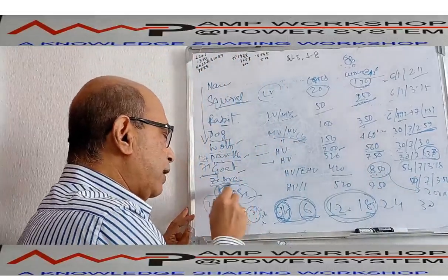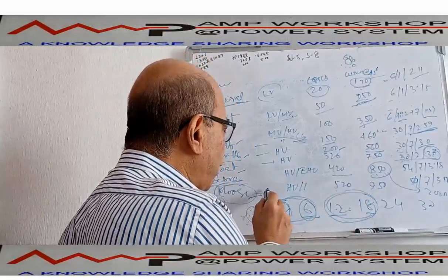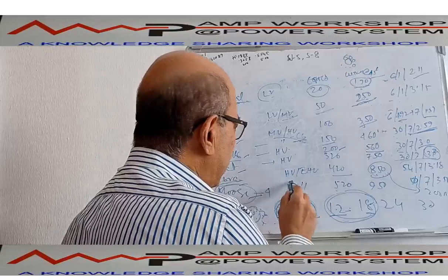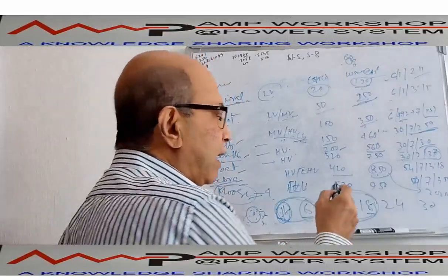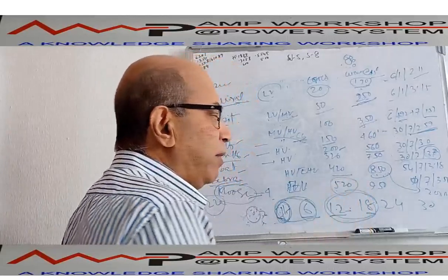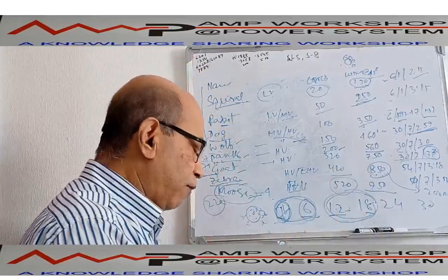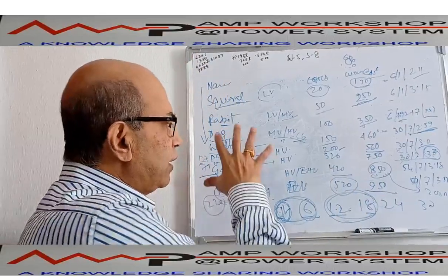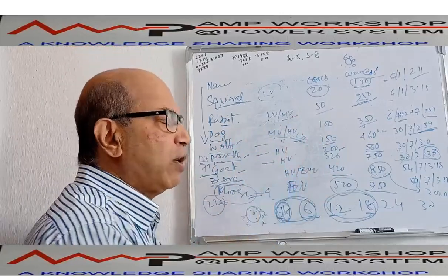And the moose conductor is a higher conductor. It is used for 400 kV lines. It is the conductor mostly used for the EHV line, up to 400 kV and upward, and that conductor area is 520 square millimeter. It can carry approximately 1000 ampere current, and that carries about 400 MVA power. So these are the various conductors we use by trade name, and that is the use of each conductor.